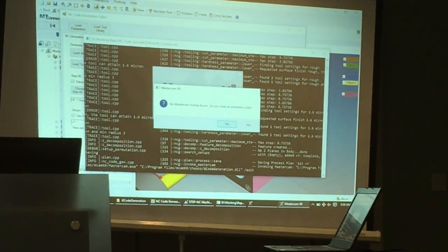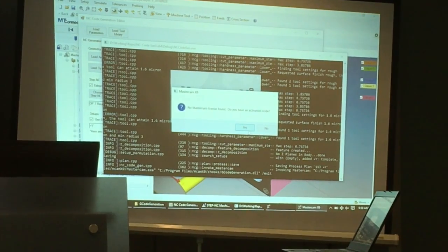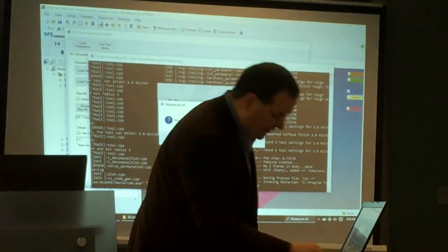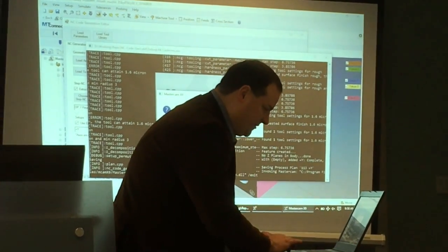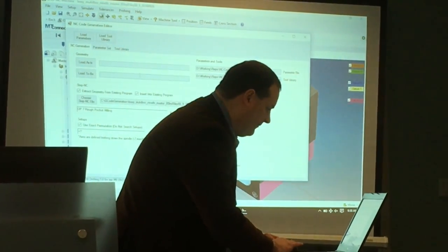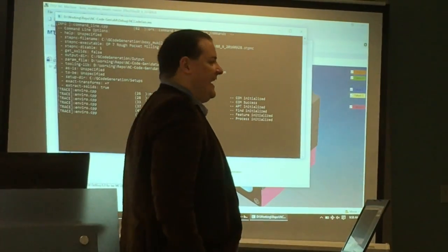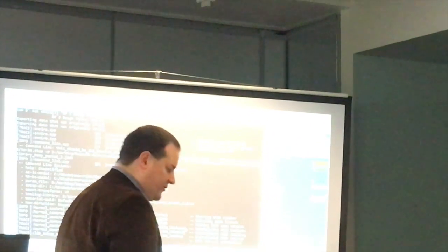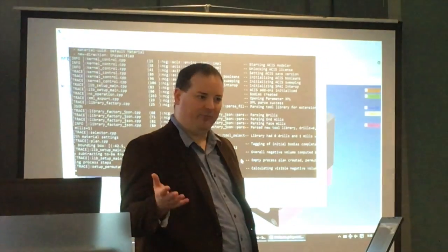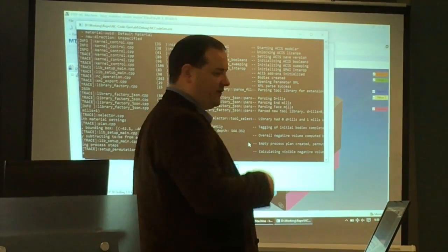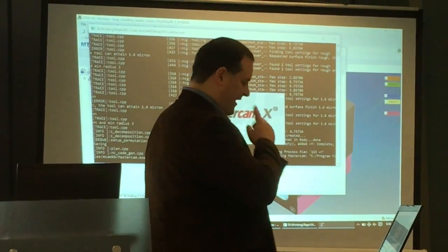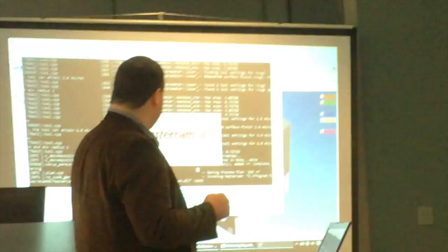So this case being fairly simple, the removal volume decomposes into a single visible volume. The visible volume decomposes into a single prismatic volume, a prismatic volume having sides that are all parallel to the machining direction and equal height. We call that a candidate feature. We will run some analysis like manufacturability analysis to determine if we want to actually remove that in a given setup. Then we'll do sort of a depth first heuristic search. In this case, the visible volume decomposes into a single prismatic volume, and that will be a single machining feature, so it's kind of trivial.